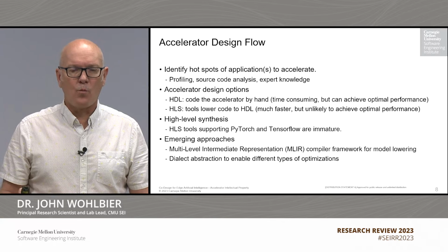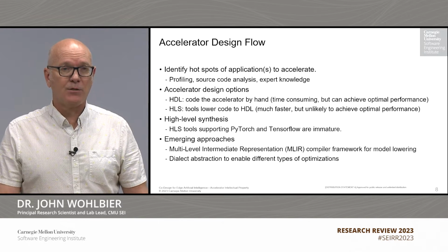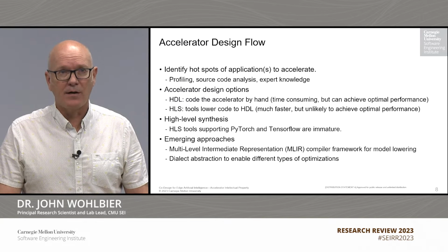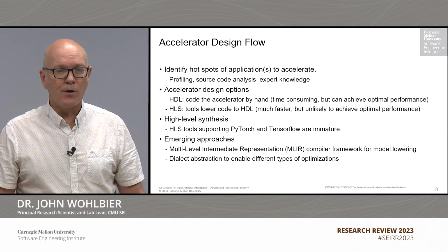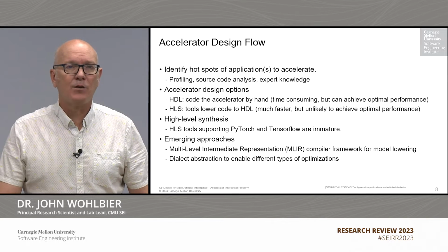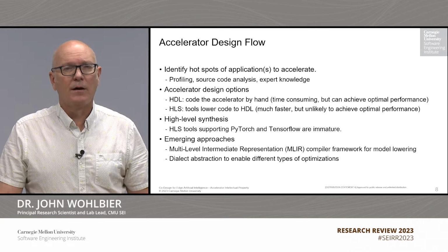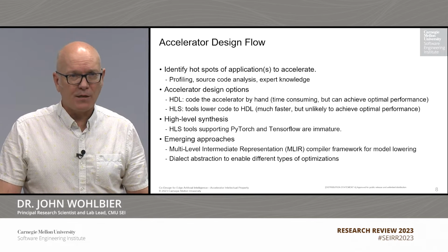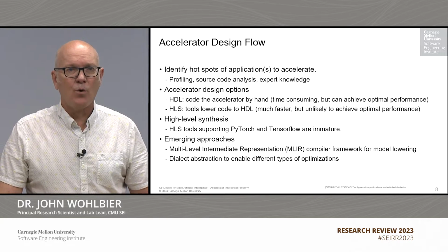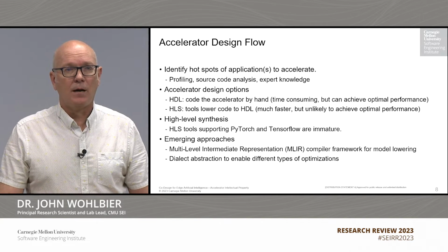So the first step in getting to your system on chip is to actually design an accelerator. What you want to do is you take your application, you identify hotspots in your application that you want to accelerate, because you can determine that acceleration of these particular pieces of the application would improve the energy efficiency of the whole system.